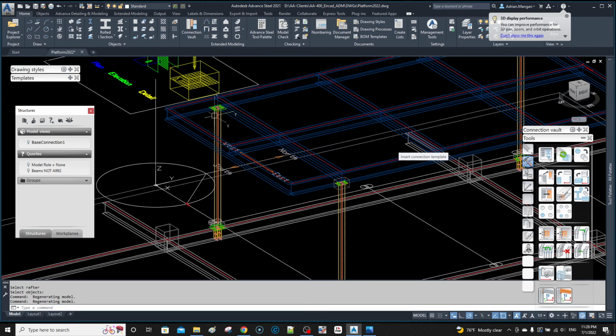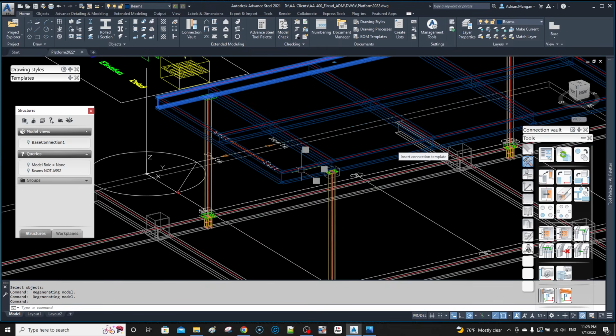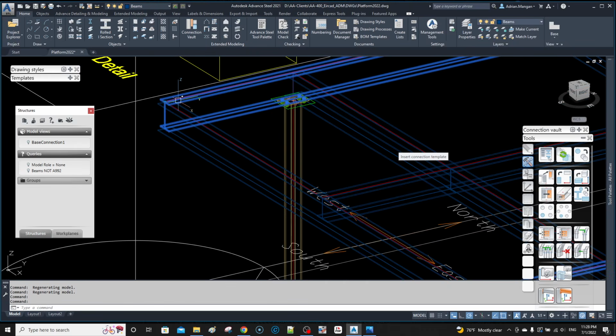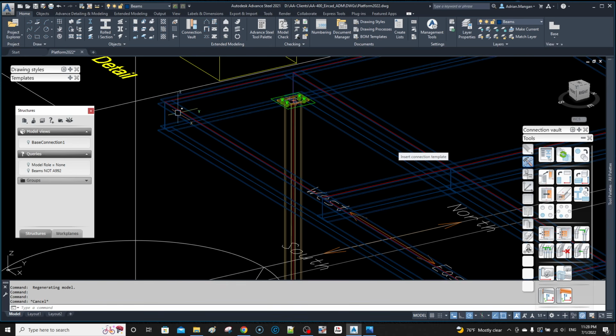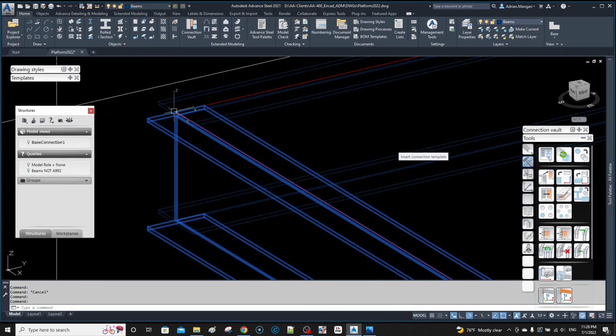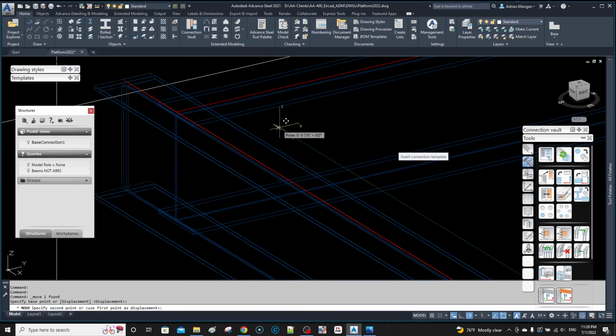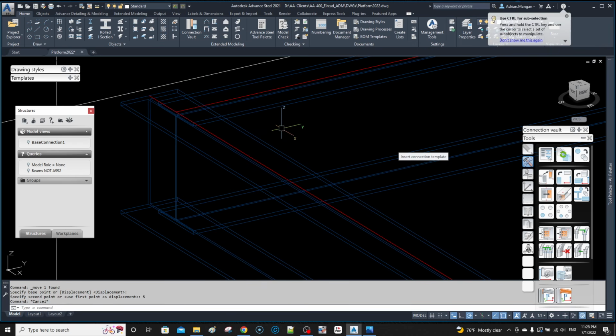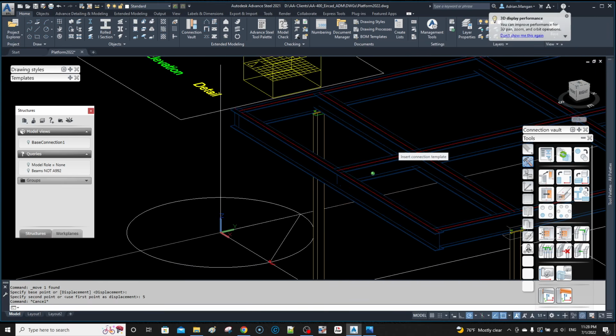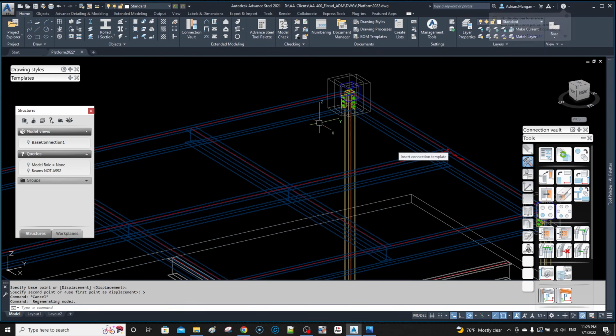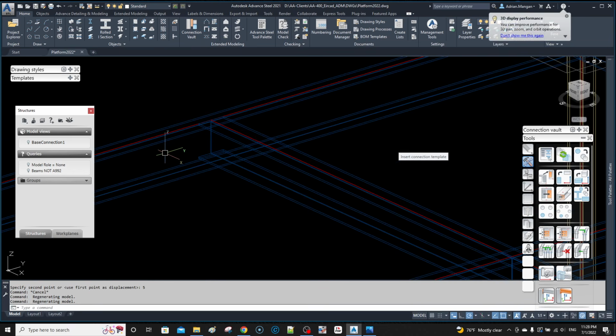So as you can see, I need these to be a little bit longer. I'm going to use 4-inch clips out here. So what I should actually do is, visually it might be better to extend this beam. So what I can do is extend this 10 inches, because I want to go 5 either way. So I generally will go 10. The beam is still highlighted. Then I'll right click and then just move it back 5 inches. Okay, so that looks pretty good. So we're okay. So now we're going to put some clip angles in here.